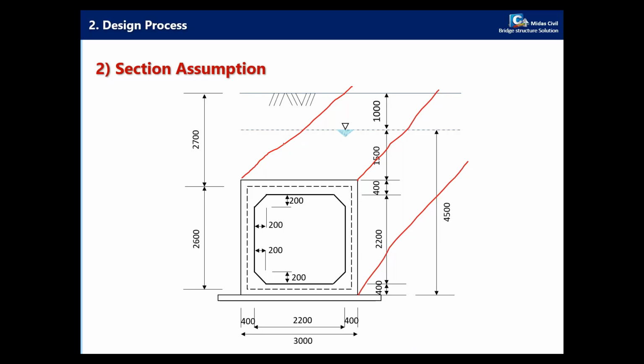So for the section we are going to use, in this direction, we are going to take 1 meter, and then the upper slab, as you can see here, has 0.4 meter of thickness. And then the wall also has 0.4 meter, and the lowest slab thickness is the same for all. The thickness is constant for all the structure.